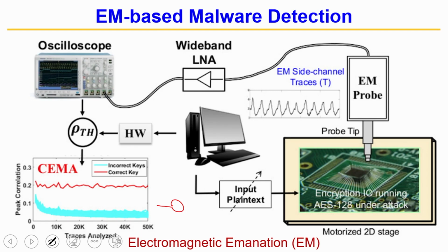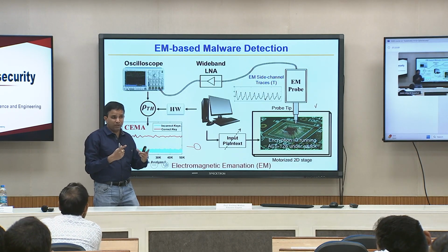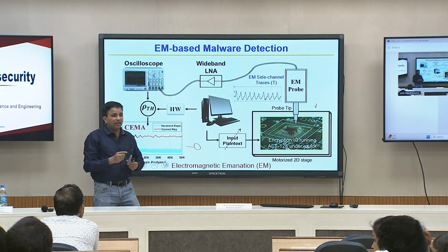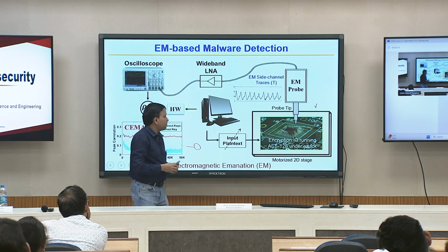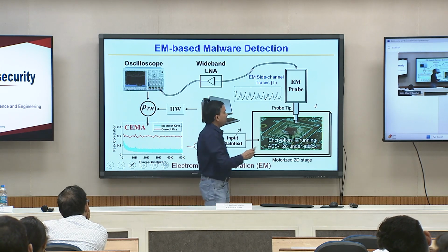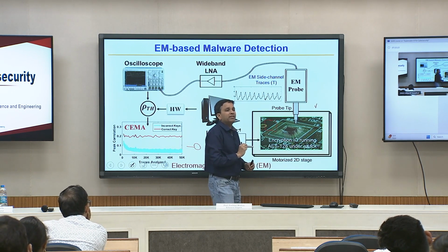But these days, if you are buying high end probes, those are very microscopic probes and they move in every millimeter across the surface and collect the electromagnetic emanation. So capturing electromagnetic emanation itself is an art, because even on an FPGA you are trying to capture, first of all you have to know where your logic is and which power supply in that FPGA.